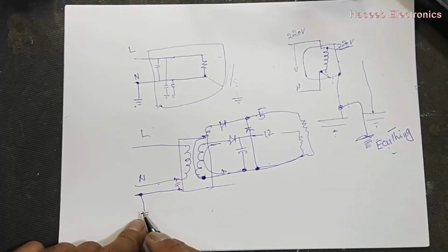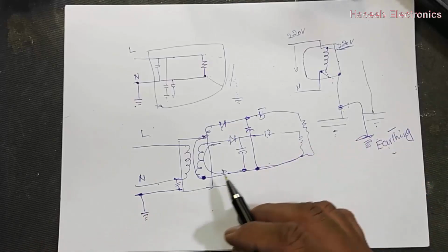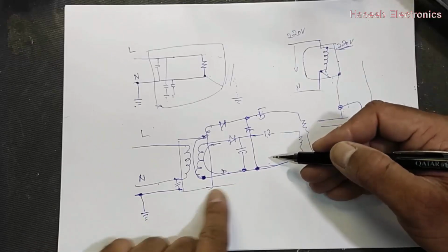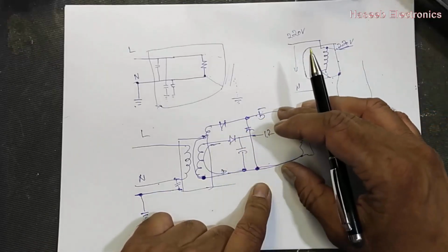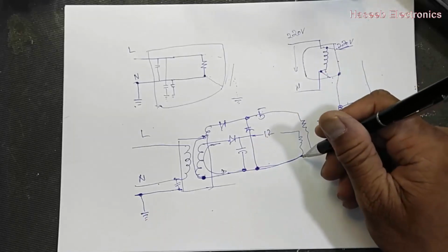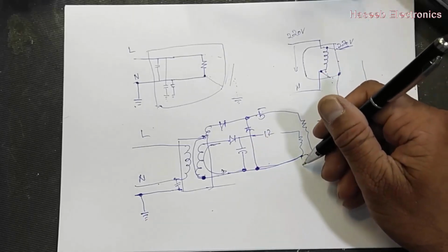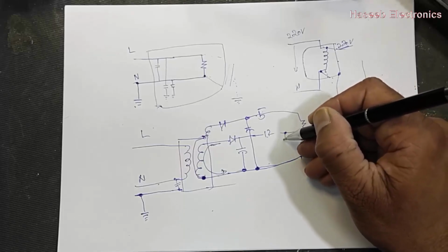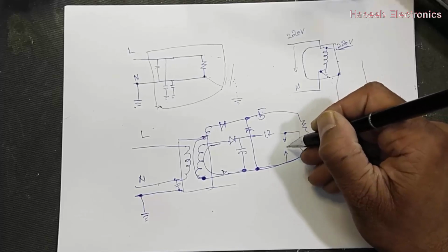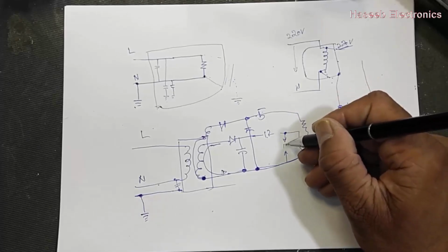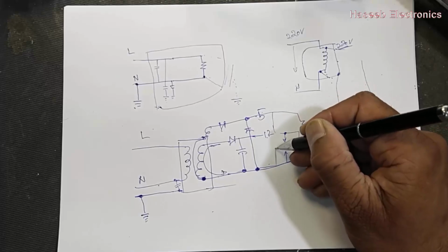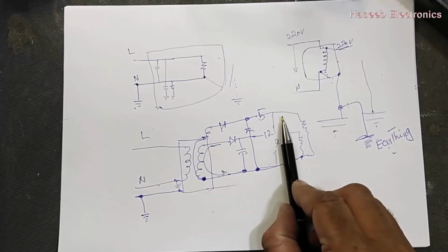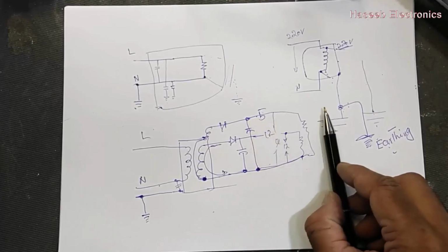So when we have a high resistance between any earth and any source, a return line or anything, that is the floating voltage. Now we will not find anything, because if we check voltage from here to here, it has 12 volt. From here to here we have 5 volt. So these floating voltages are separate.